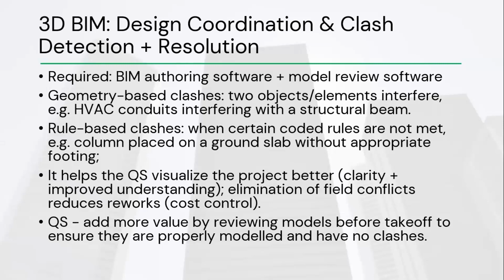Because if we go to site and find these interferences and try to solve clashes while we are working on site, that is going to cost us more time, because we'll have to start coordinating the design while on site, and that time would have been used to do other more useful activities. And in that case, if the contractors had already done the construction, you'll see cases where there are reworks, and that comes with a cost implication.